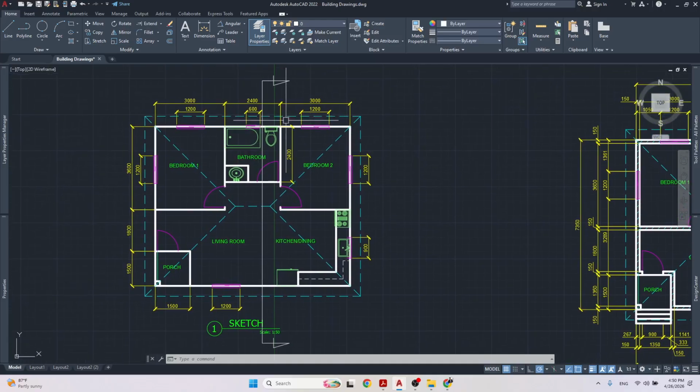As you should know, a full section drawing is a cut that is from the roof, straight through the roof, all the way through the walls, through the floor, down to the foundation. So where this line runs is where this cut is going to happen, and then we are going to be looking in the direction of where these arrows are pointing.